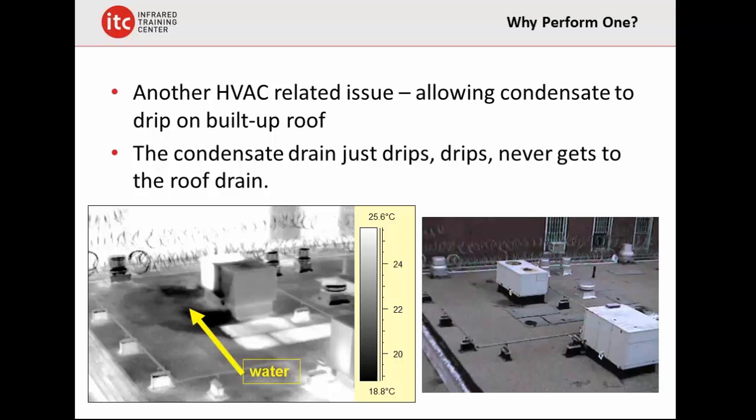That's right. You have to understand that if we do an electrical scan, all we have to do is tell our client we want to have our building loaded at least 40% of its rated amperage load is ideal. We can't say we're coming tomorrow night and we're going to guarantee that we can do our infrared roof scan. Unfortunately, you can't do that.